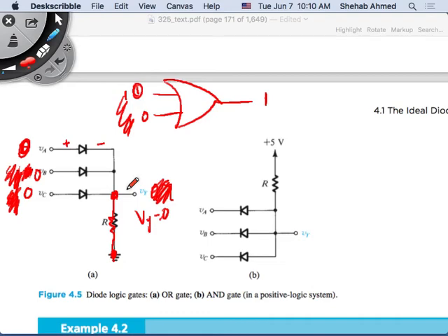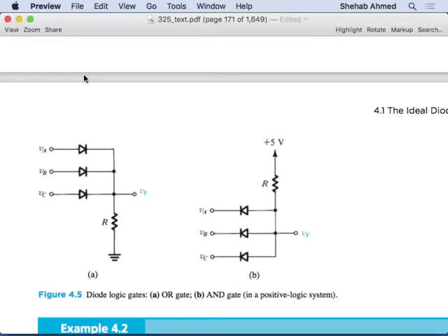Yeah, in amplifiers, you were clipping because of the voltage, for example, right? If you add diodes around the op amps, for example, you can block before you start clipping due to the gain. So we will look at circuits like this, and then there's a whole chapter dedicated to even more circuits like this, combining op amps and diodes, that we will not cover, but I will briefly refer to. Anyway, this is another application of diodes that I wanted to demonstrate to you.